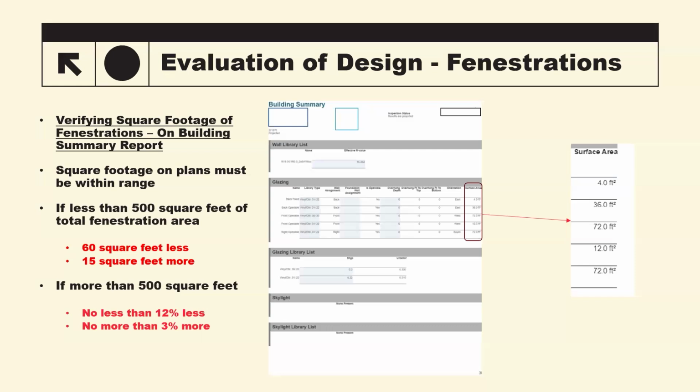Yeah, absolutely. Perfectly said. I still get calls from building officials or plan reviewers who call me or send me an email and say, "Here's what I get. I get one wall for the entire length of the house. It's just one wall listing all the windows." I do understand that doing a REScheck, now that it's the newer versions, asks you to break everything out into walls. So you build a window and then assign each window to each wall. That way it actually has the orientation.